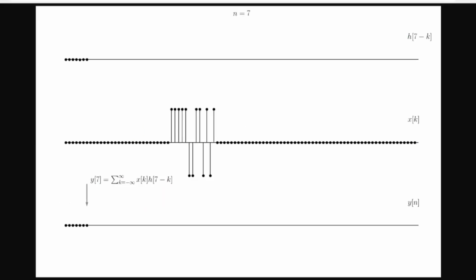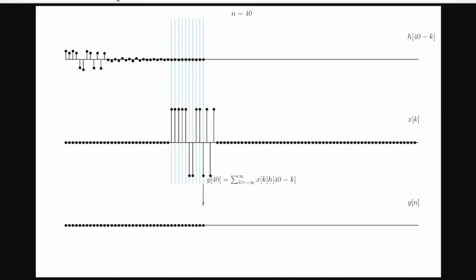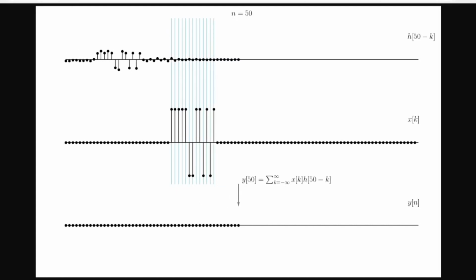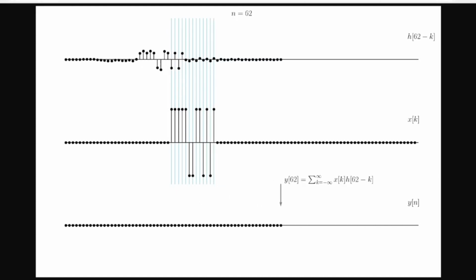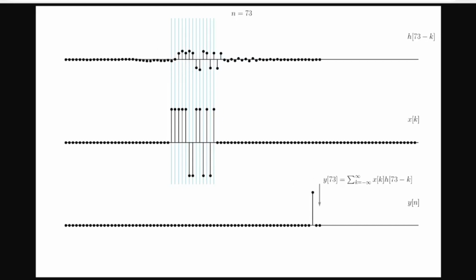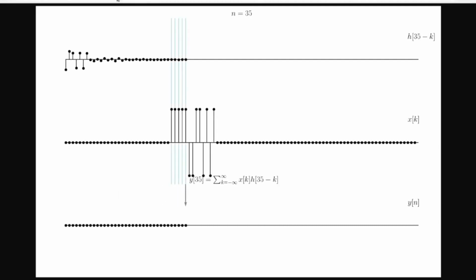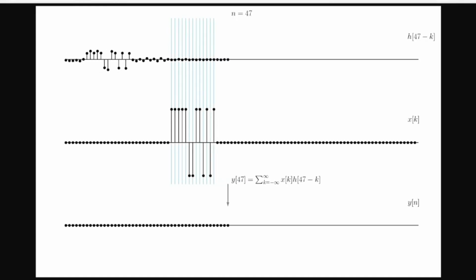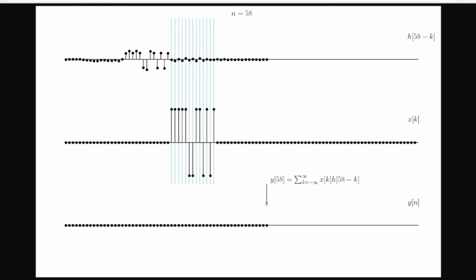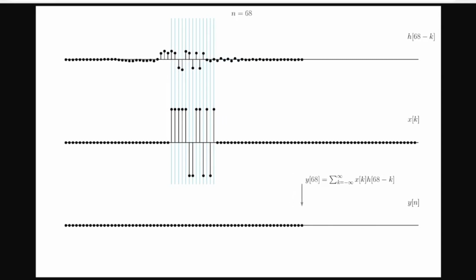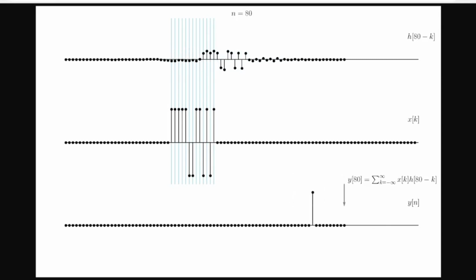This animation shows the process of convolving a radar echo using an inverse filter. The inverse filter is shown above. The middle plot shows the simulated radar echo. Because we have radar scattering only from one range, the radar echo is a delayed version of the transmitted signal, epsilon of t. This is therefore what the 13-bit Barker code looks like. The bottom plot shows the output of the received radar echo convolved with the inverse filter. The output of this convolution operation is an unbiased estimator of the true scattering of our simulated radar target, which only has scattering from one range.